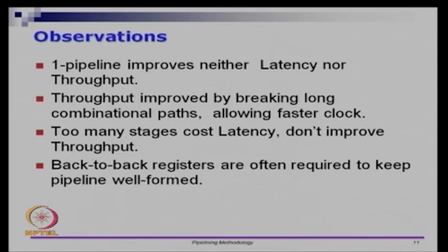Too many stages can cause latency without improving throughput, and back-to-back registers are required to keep the pipeline well formed. So, these are the observations. I have talked about this with pictures also, but these are the observations that I am making from all these things. It is a summary of observations.